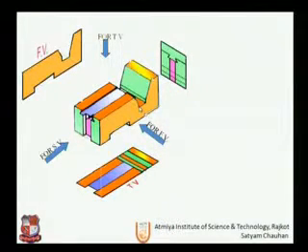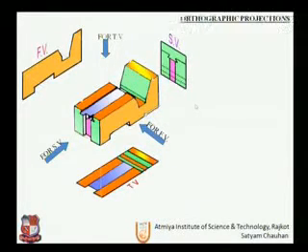One line for this slot and one more line for this slot. For the slot, both hidden lines are overlapping, so it is to be drawn only once, and the upper hidden line is for this slot to complete the side view.